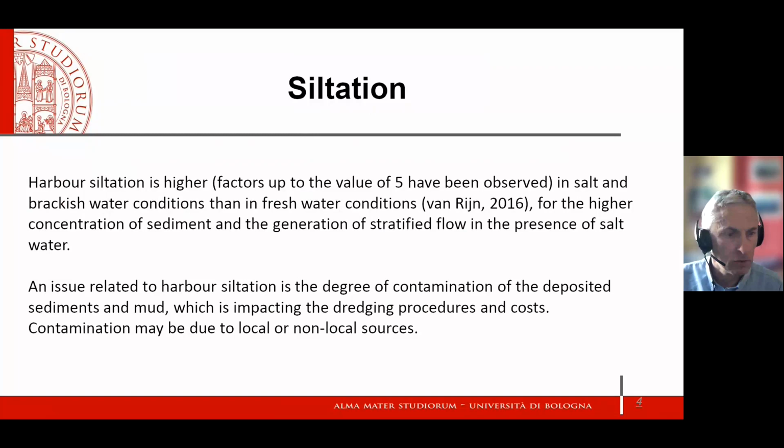And the reason is not only a higher concentration of sediments. Of course, we expect in brackish waters and salt waters a higher concentration of suspended sediments in the flow. But there is also the effect of the stratification of the flow, which occurs in salt waters and brackish waters. And this stratification is also favoring the settlement of sediments.